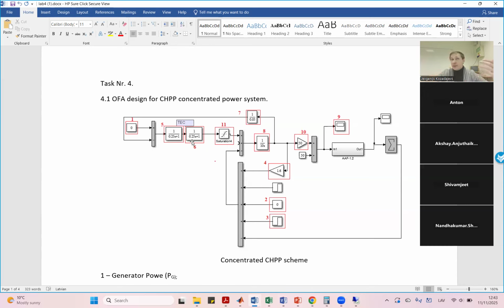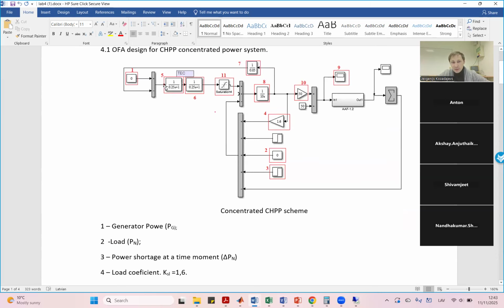And so the steam turbine has slightly different parameters. As a result, we have different control for the steam flow instead of the water flow for hydro. That's why we have this difference, yes? And this difference is represented by different transfer functions. This is for your use, number 5 and number 6. To simplify your task, we could use two similar transfer functions for both.